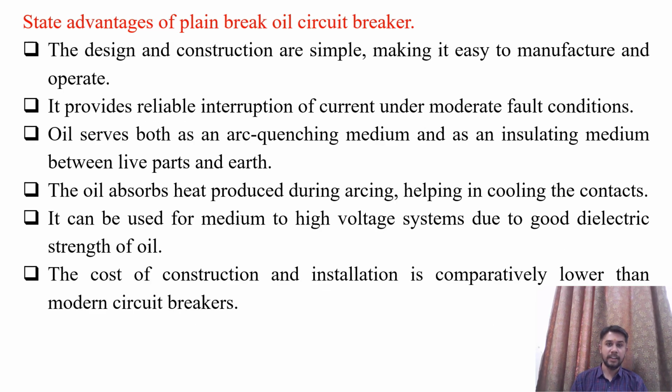Advantages of plain break oil circuit breaker. There are several advantages of this type of oil circuit breaker. One is that the design and construction are simple, making it easy to manufacture and operate. It provides reliable interruption of current under moderate fault conditions due to the cooling efficiency of oil. Here oil serves both purposes. First, it serves as an arc quenching medium, and second, as an insulating medium between live parts and earth. So oil is the only medium necessary for quenching as well as insulation.